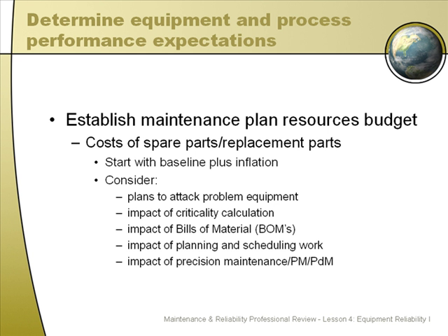In many cases, particularly in older operations where computer technology didn't exist when the storeroom was begun, spare parts inventory could have gotten quite out of control because things are normally stocked when they're needed and documented poorly and then utilized throughout the plant, even on equipment that they weren't intended for in the first place. You need to get this resolved because it's really the key for how you can reduce storeroom inventory in the future. A bill of materials ties each part to the equipment it's used on and tells you what it's for.